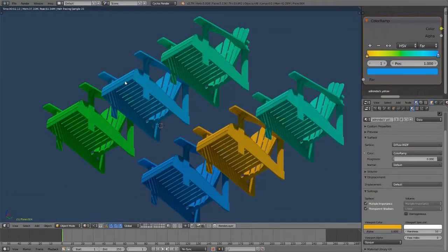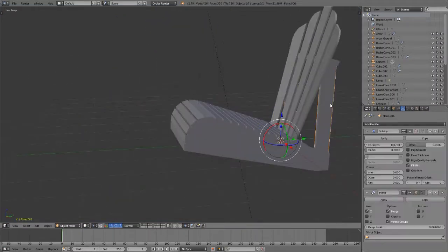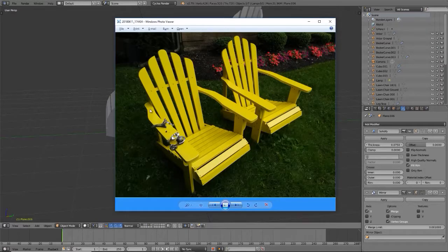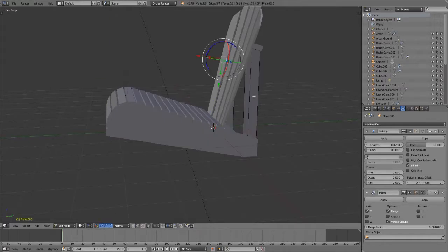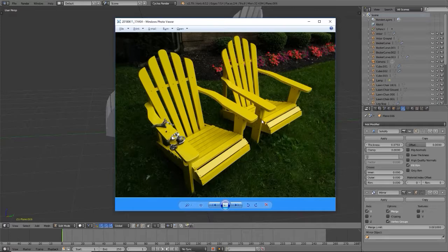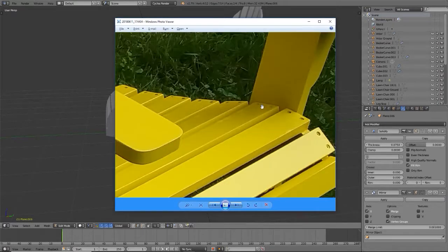Okay, here's a straight part that has modifiers solidify and mirror. The next straight part is going to be the arms, but here's something I learned yesterday. That straight part really wants to be built from a curve, so why don't we move to the forward brace? A, to select it all, change your transform orientation to global, and then Shift D, Y. Move them up. Move them where up? Move them kind of to the introduction of that hump that holds the seat slats.